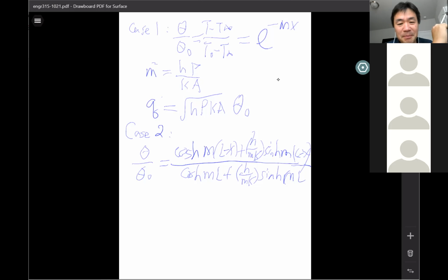Dr. Sang, whenever you say cosh m times L minus x, is that times? No, it's not times, it's cosh of. mL minus x is all inside the cosh. That's the whole argument. Good question. I should put the parentheses there, but the equation looks too complicated. The textbook didn't put the parentheses there to group m times L minus x. These are all inside the cosh.